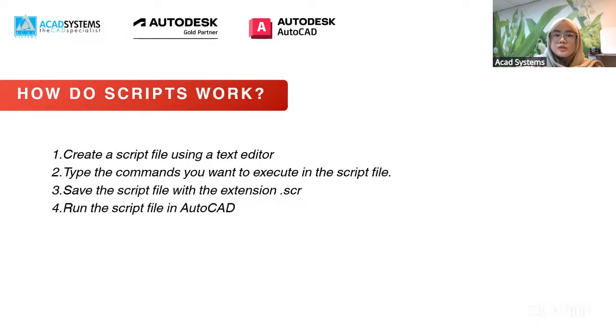And how do scripts work? First, we have to create a script file using a text editor and then type the commands you want to execute in the script file. The third one, save the script file with the extension .scr and then run the script file in AutoCAD.